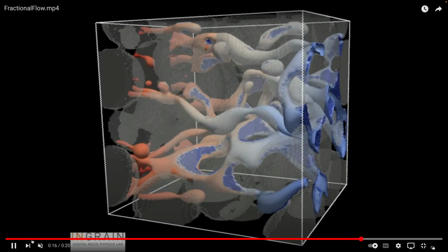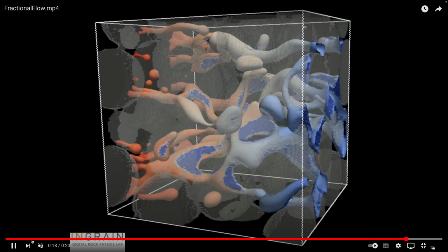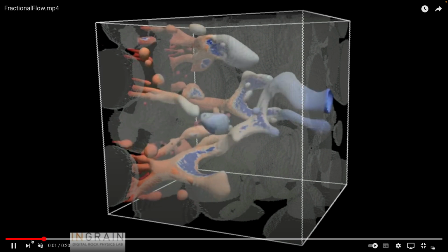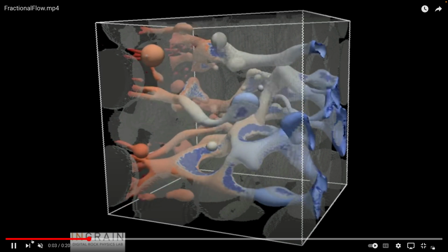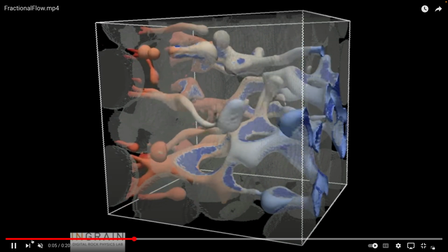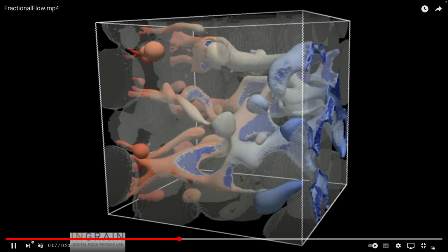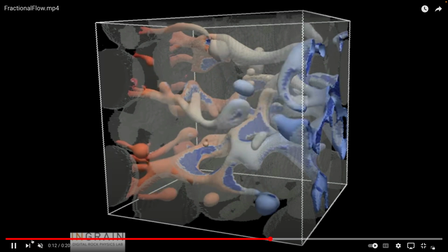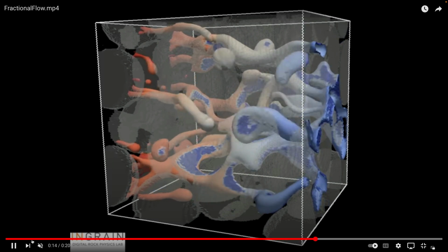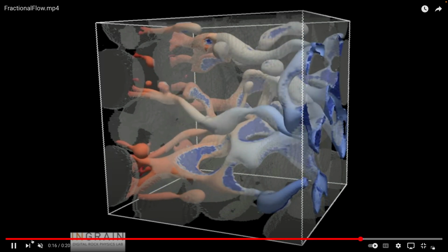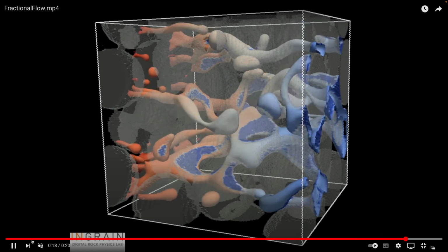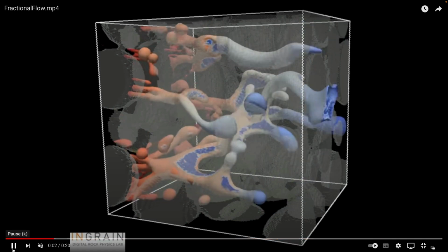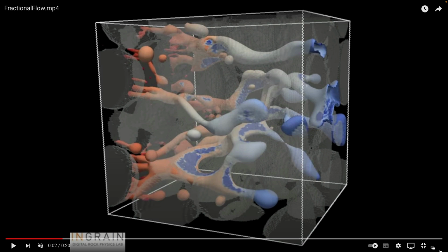And so it's a linear relationship. Or if you double the viscosity, you halve the flow rate. So it's related to a hydraulic conductivity or permeability and a viscosity. And it allows you to account for the frictional losses in the system, even though you're only using mass balance equations. And we may look at those later on today if we get to it. So that's one thing to look at.